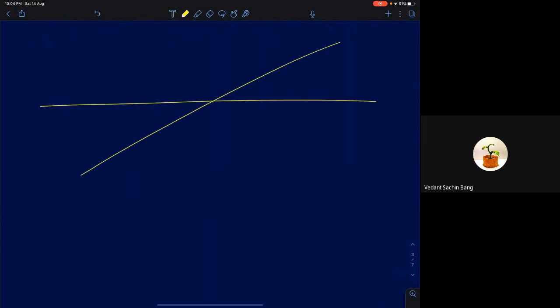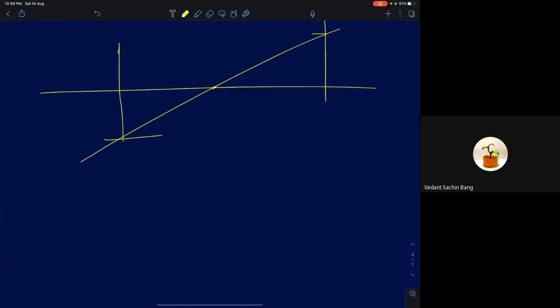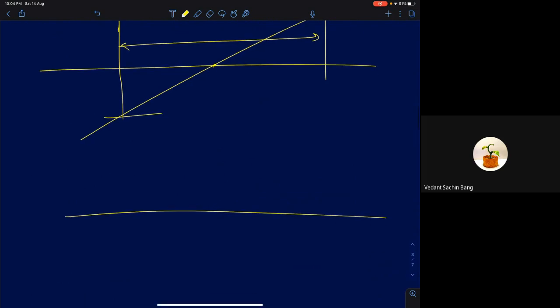So look at it this way. This is the high frequency signal, a low frequency signal. And I am interested in the voltage levels here. So this is the voltage level at this point, and at this point, until this region, noise can corrupt it. Now look at the high frequency signal. That's going to cross much faster. So it's going to do this. So to cross the threshold level, this is the region in which noise can affect its decisions.